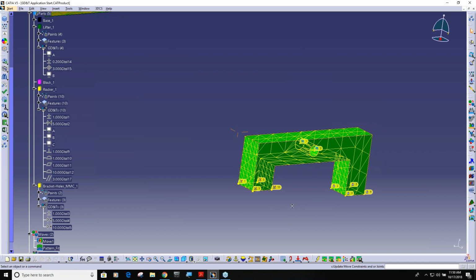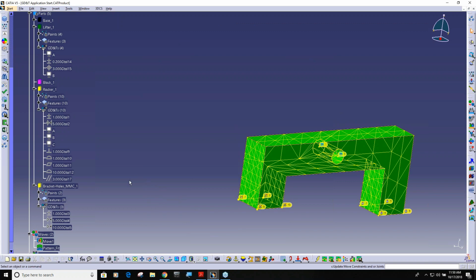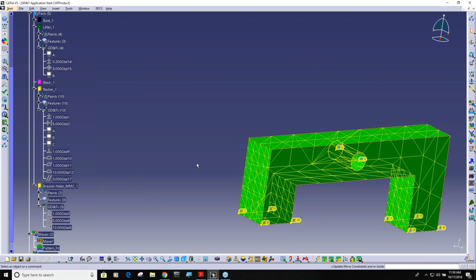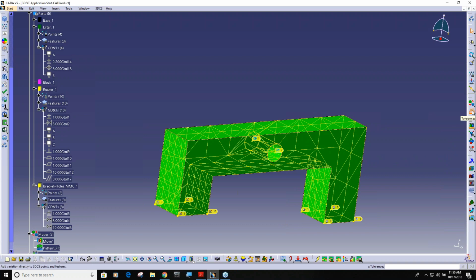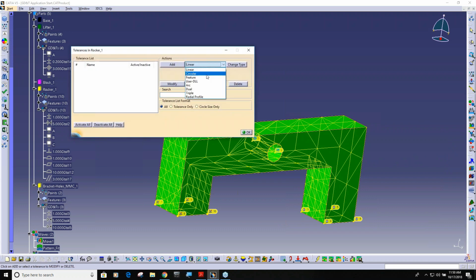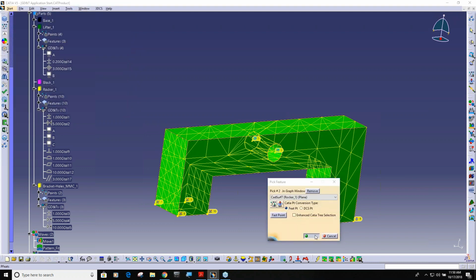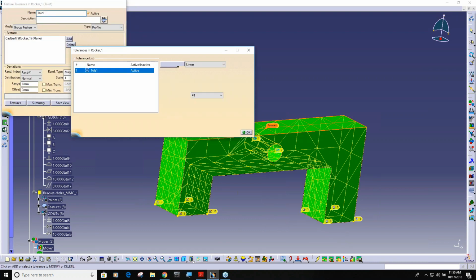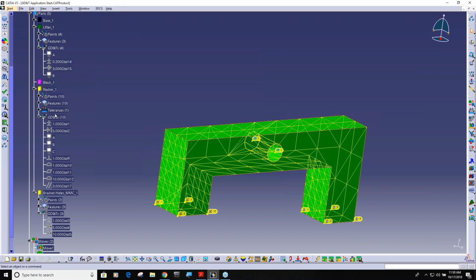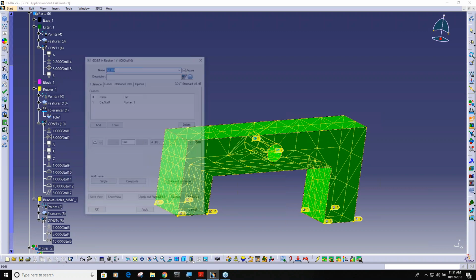Yeah, so the old tolerances, linear tolerance, feature tolerance, they're still going to be in here. In other words, now you can see there are two buttons here. I'll click this part, and I'll add feature tolerance, add, pick that surface, close. So you're going to see your conventional tolerancing for old models, and if you extracted the GD&T, it's going to come in and go into our dialog boxes, like you see here when I double click on this one.